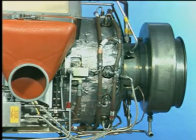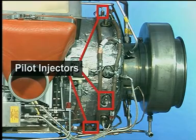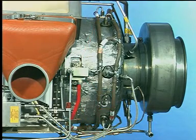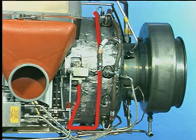During the initial start sequence, fuel is supplied to the three pilot injectors through the pilot injector manifold. When the fuel pressure increases to a specific value, fuel is supplied to the 6 main fuel injectors through the main injector manifold.